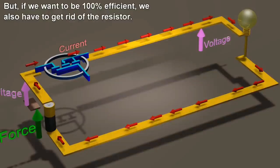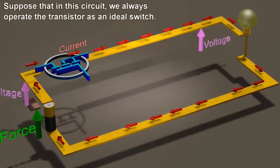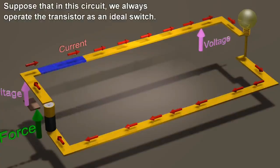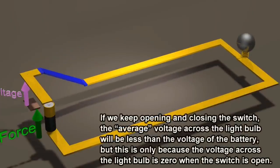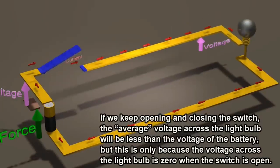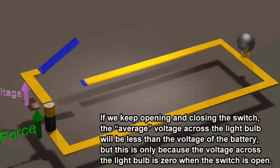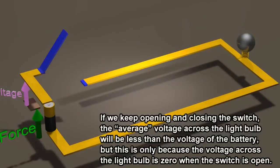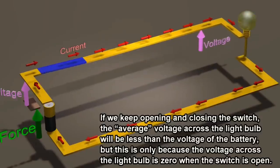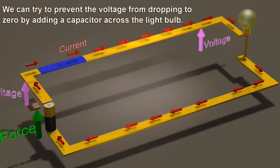But if we want to be 100% efficient, we also have to get rid of the resistor. Suppose that in this circuit, we always operate the transistor as an ideal switch. If we keep opening and closing the switch, the average voltage across the light bulb will be less than the voltage of the battery. But this is only because the voltage across the light bulb is 0 when the switch is open. We can try to prevent the voltage from dropping to 0 by adding a capacitor across the light bulb.